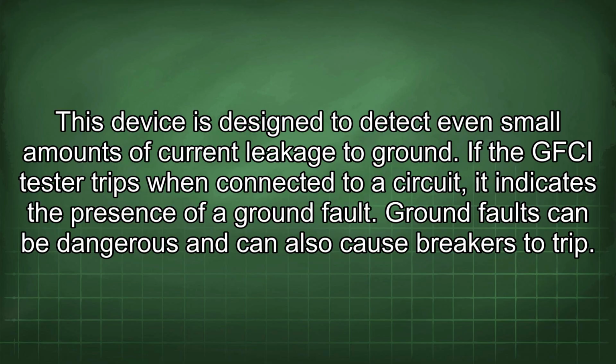This device is designed to detect even small amounts of current leakage to ground. If the GFCI tester trips when connected to a circuit, it indicates the presence of a ground fault. Ground faults can be dangerous and can also cause breakers to trip.